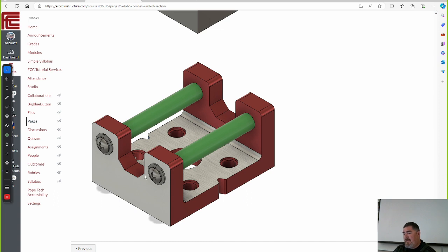So here, if we're in that assembly, what do we probably care about seeing? Do we care about cutting the whole thing in half here? What's more important that we might care about? Seeing what's going on. Yeah, the bolts. What's going on in the middle of here? Is this going into there? Does it stop there? How's the screw line up? How deep is the screw into the piece? That's all stuff we might care about, right? So probably just a full section through one of these rods might be what we do. Or a broken out just on one corner of it here.